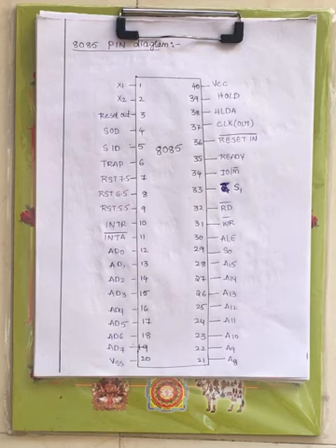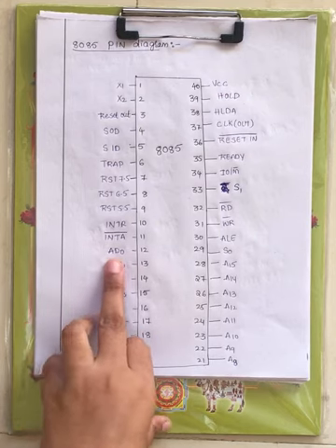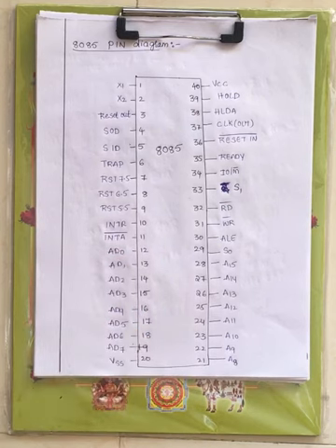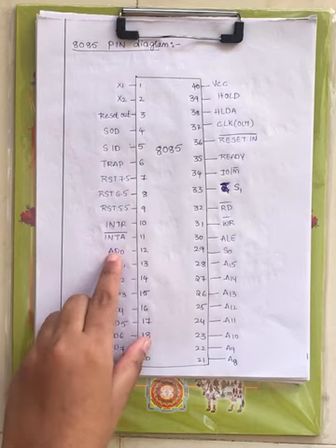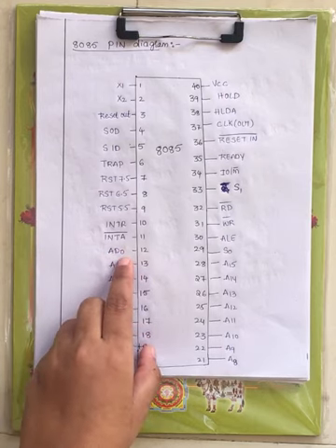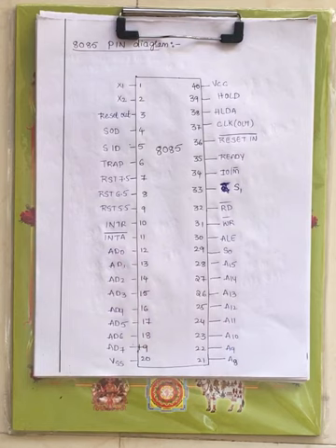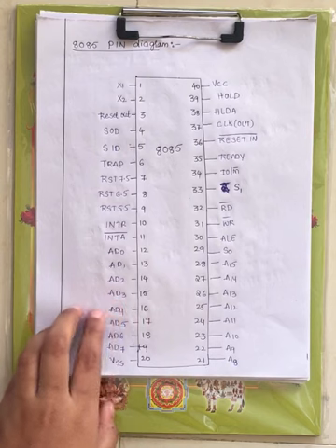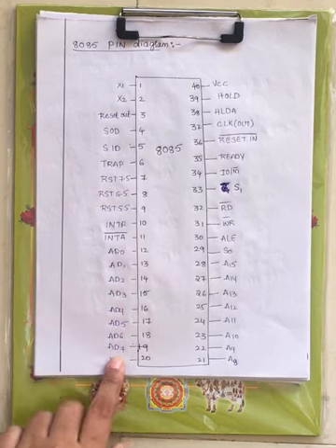Under that bus we have seen three different types of buses. What are those? Address bus, data bus, and control bus, right? Now here A stands for address, D stands for data. Multiplex, you know the meaning of multiplex, combining. Here address bus and data bus are combined with each other: AD0, AD1, AD2, AD3, AD4, AD5, AD6, AD7.